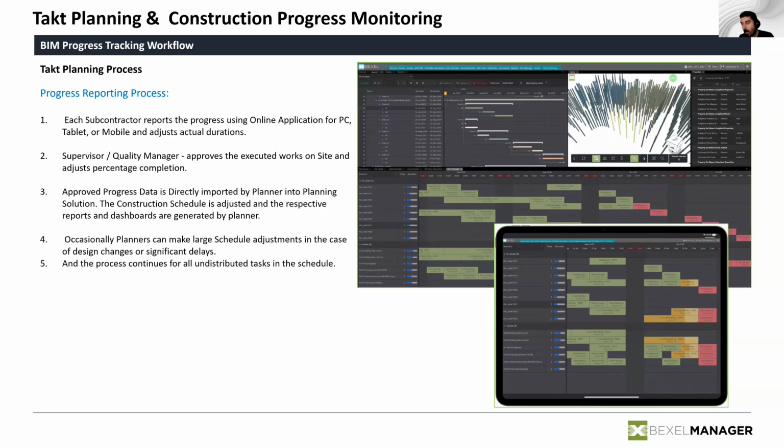So they're going to know for which pile they have to do which activity, for instance, and then they're going to be able to simply, very often, very easily report if this micro task is completed. It is much easier to simply say, okay, today we completed pile 1007 and 1008. And we completed the drilling, and we also completed the concrete pouring for 1006. Then to simply, at the end of the week, say the area 4C is completed 25% or 30%, because that number doesn't mean much to anybody who's looking at the big picture.